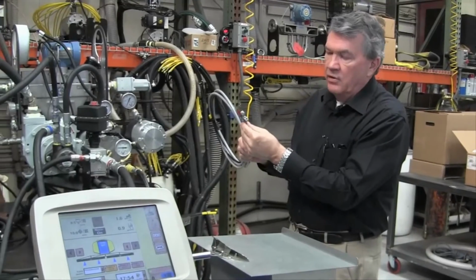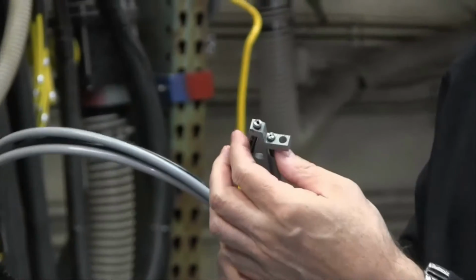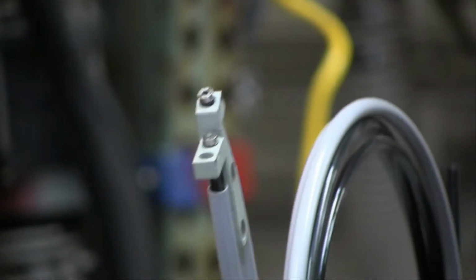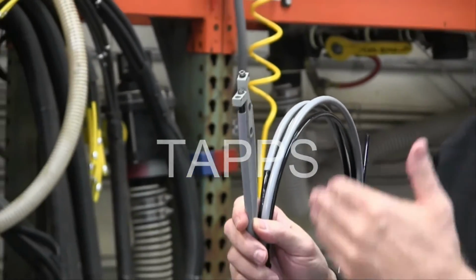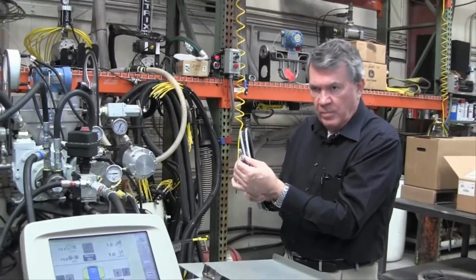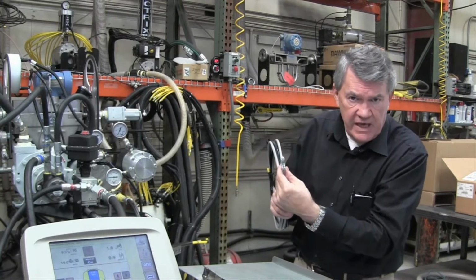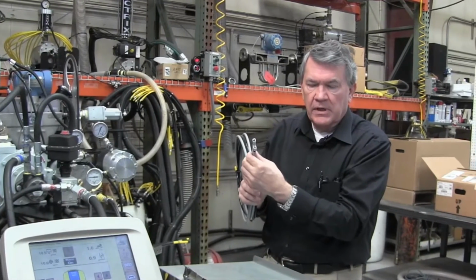Here's another view of an orifice group that has been utilized in the system, and you can see the two lines coming together, and if you get a side view, they're trying to collide and mix the material to make triammonium polyphosphate sulfate. So it takes two pumps, two systems. It takes a liquid system and an ammonia system with high pressure to perform this chemical process. It's a physical process because the application is made at 1% CV, and it's a chemical process because we're able to combine the two materials.